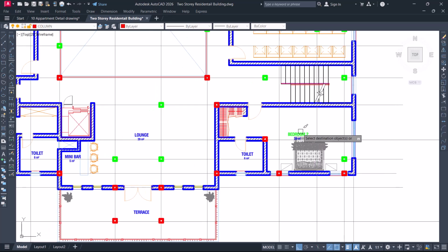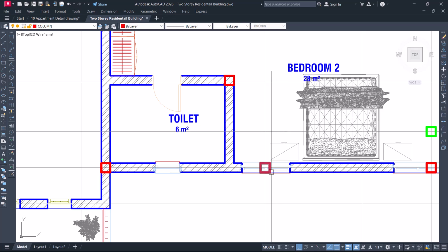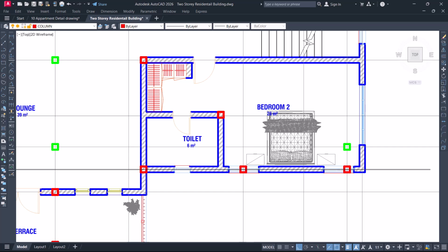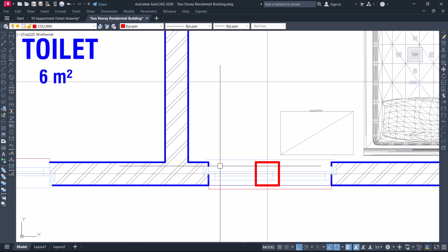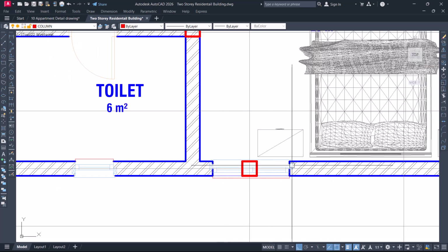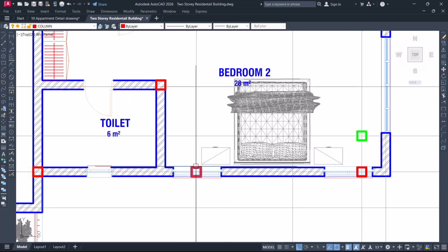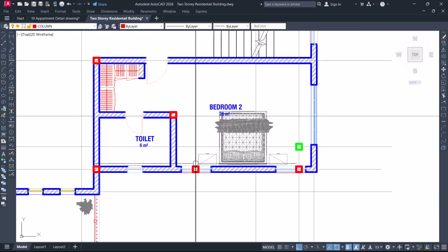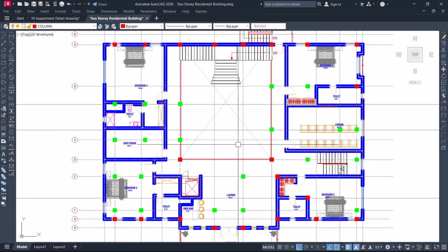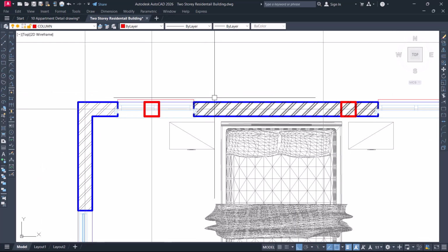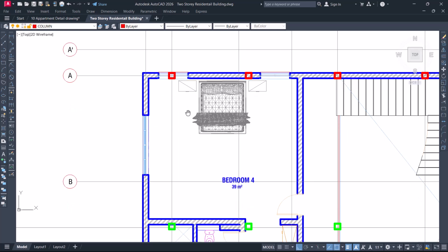The ones that are passing through maybe the window, I can choose to stop it, or I will advise the person that did the drawing to shift the window, at least they have space. Although it will change his design a bit, if there is need that this column must be here for this structure to be stable, then we will leave it there. This one also, they will shift this window off from this point, because they have space here. Okay, that's fine.